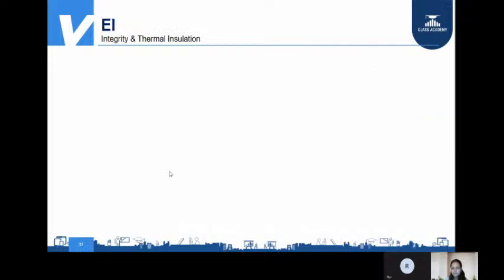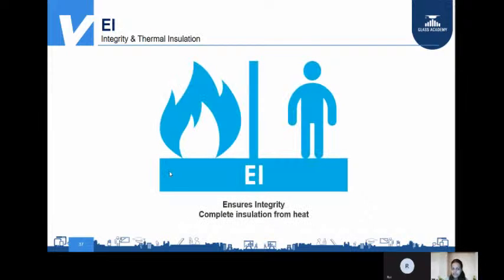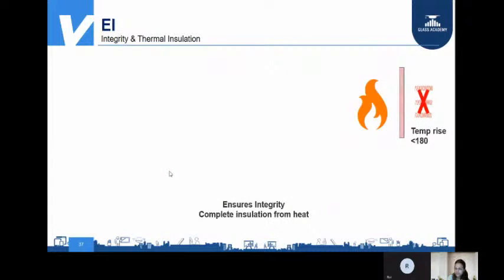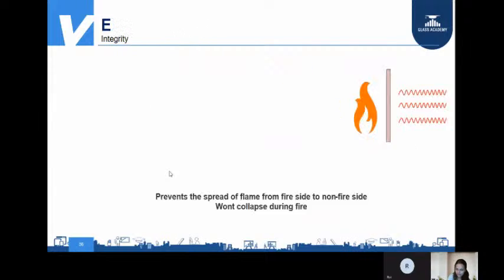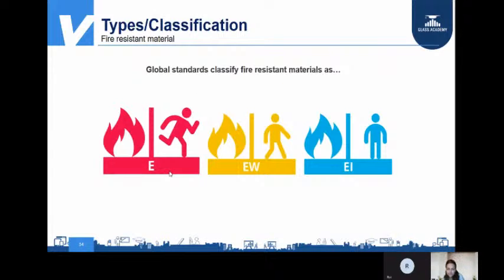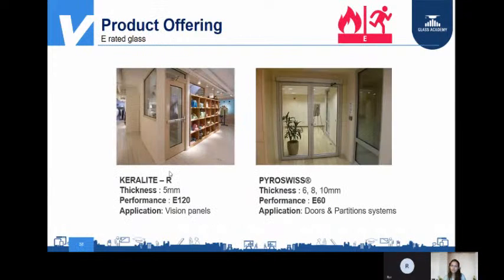And the fourth type of glass we have is the insulated glass unit, IGU, or we can call it DGU also. So what happens here? You have two glasses and there will be an air gap or cavity in between. This can be filled with air, or it can be filled with gas. Then we have ceramic fritted or digital printed glass. You can do enamel painting or ceramic printing on the glass here.